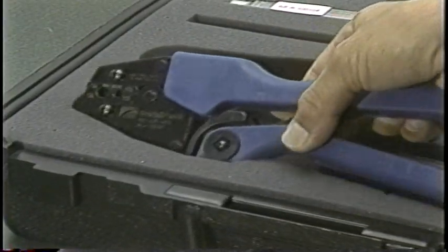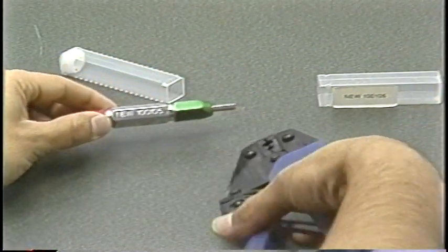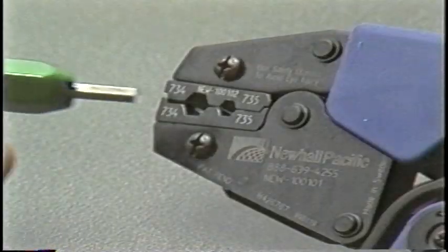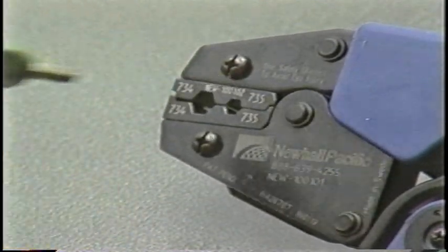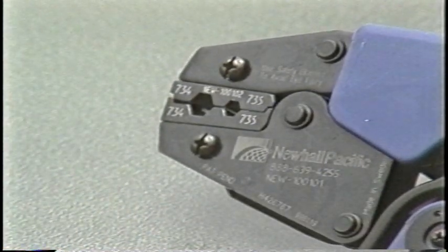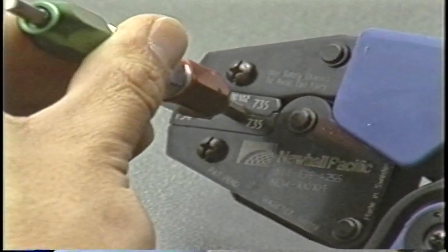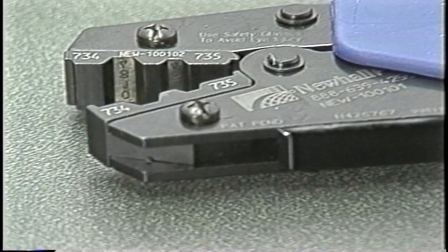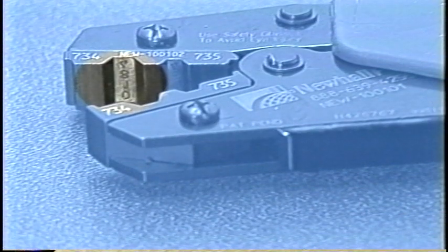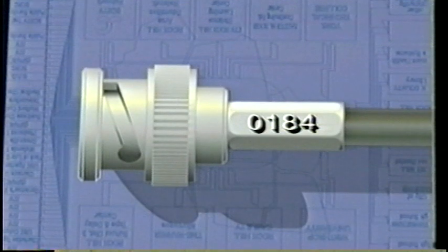Select the correct crimping die. It is important to remember that the hex crimp tool must be verified daily before use using the hex crimp gauge. For traceability, the die faces are inscribed with the serial number. This inscription leaves an imprint in the crimp sleeve that allows each termination to be traced to a specific installer.